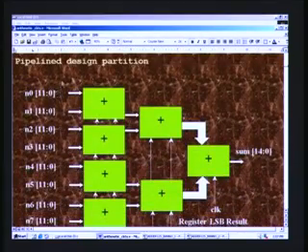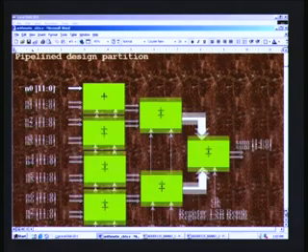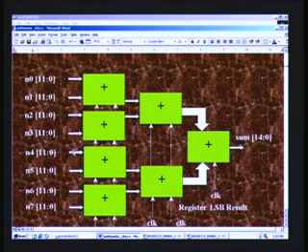So this partition of the design can be in this fashion. This is an algorithm evolved by the speaker for the sake of the DCTQ application, and here in this case we have 4 adders adding at one stroke, that is concurrently, and thereby speeding up the process, and also having pipeline registers internally. So these are all the clock inputs here, that means there is one register inside here as well as here, and this register